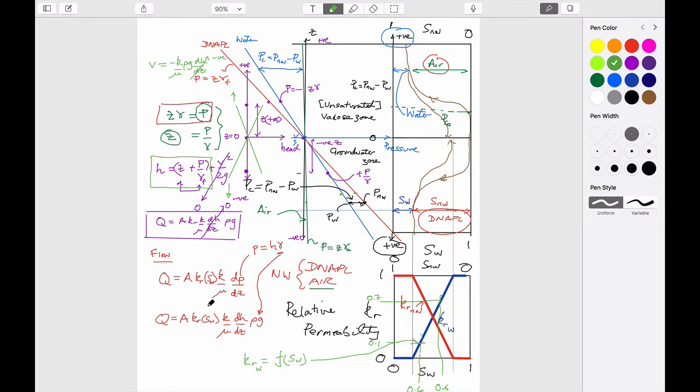And if we know that, we can use that directly in Darcy's law, and we can say something about rates at which fluid flow occurs, volumetric rates. And if we make this connection between pressures and heads in a very simple way, we can make a distinction by measuring heads as to whether flow in a gross sense is occurring upwards or downwards.